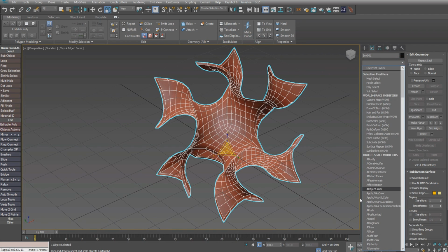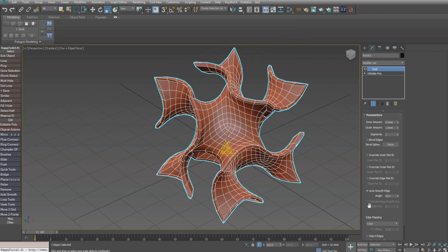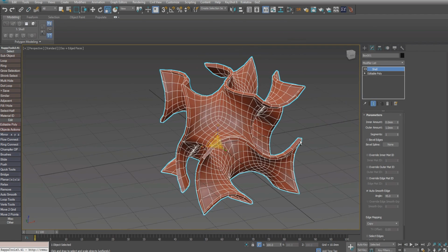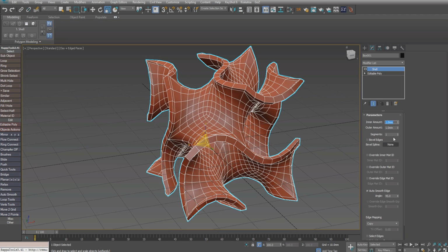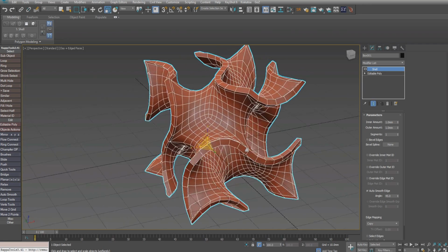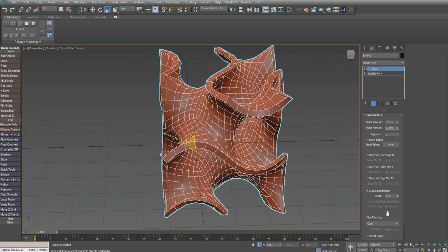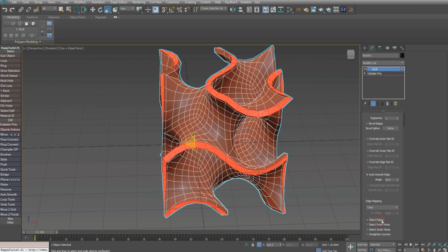All right, so at this point, we can thicken the object. We'll add a shell modifier. And if we do take this to 3D print, which I'm not sure I will, but we'll want, most materials require 2 millimeters of thickness. So to make that an even border, I'm going to use an outer amount of 1 millimeter as well as an inner amount of 1 millimeter.